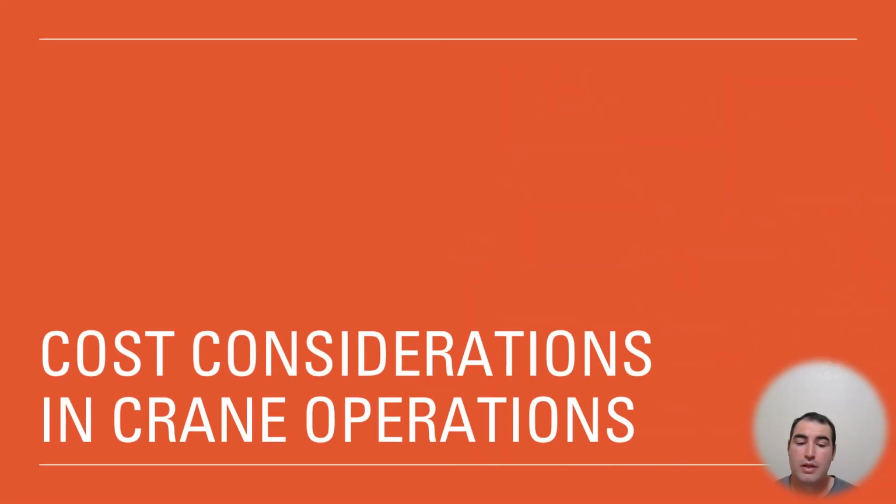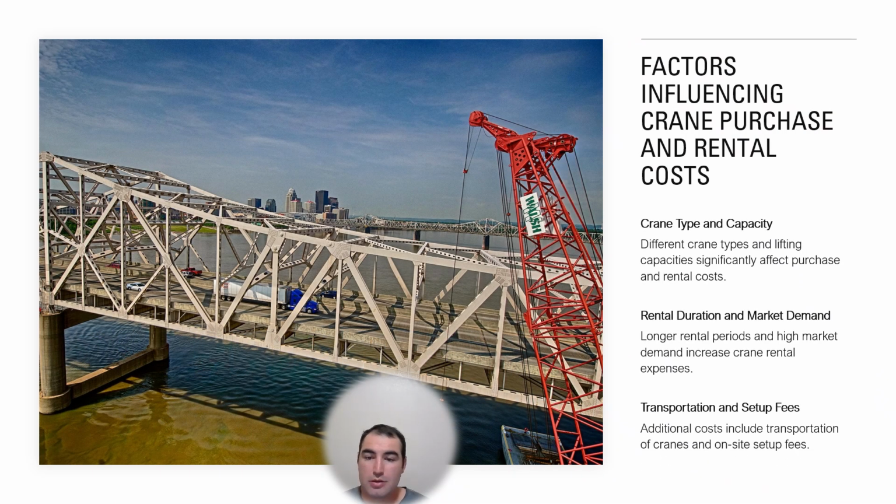Now we'll be going over the cost considerations in crane operation. Some of the factors influencing crane purchase and rental costs: crane types and capacity. Different types of cranes and lifting capacities significantly affect the purchase and rental costs of cranes. Rental duration and market demand. Longer rental periods and higher market demand increase crane rental expenses. Another big one is transportation and setup fees. Additional costs include transportation of cranes and on-site setup fees.